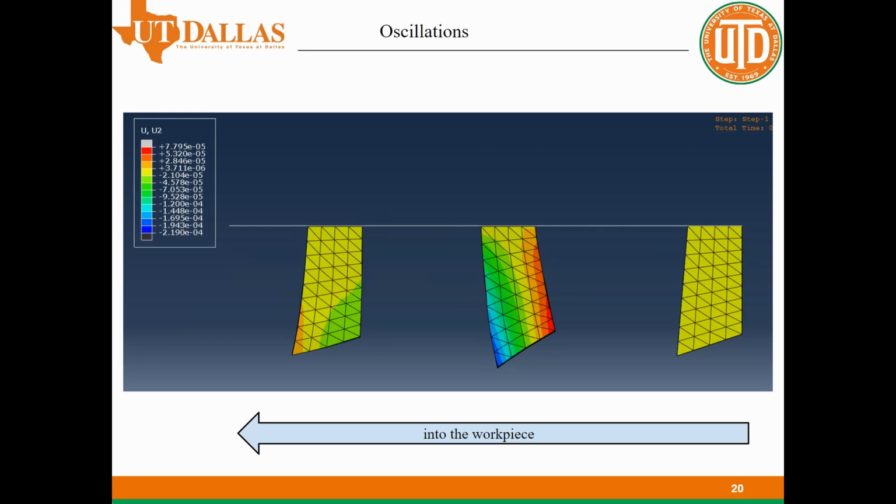We realized that the entire blade tends to oscillate left and right, which results in the cutting edge moving vertically relative to the workpiece. The scale factor here is exaggerated, but you can clearly see how the height of the cutting edge varies as the tool moves through the aluminum block.